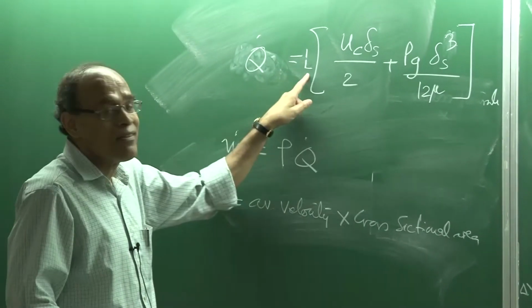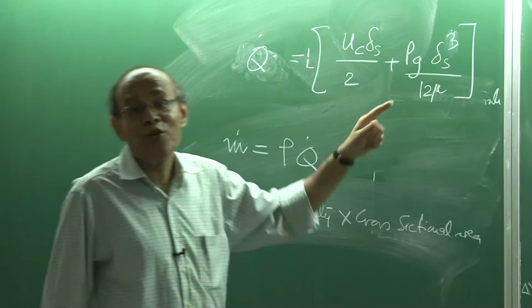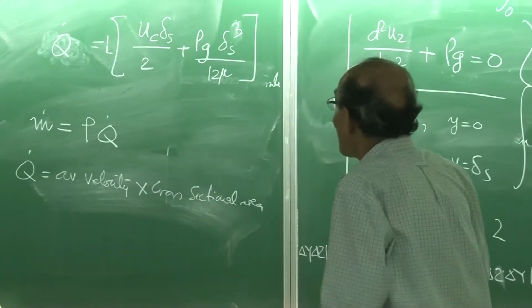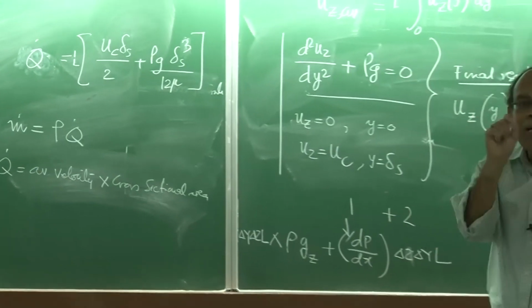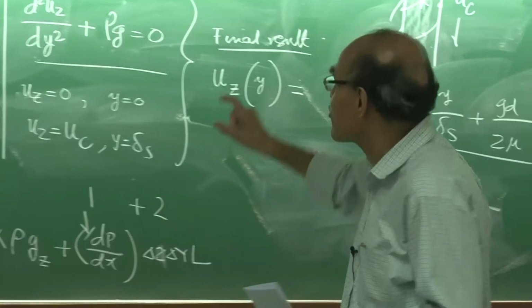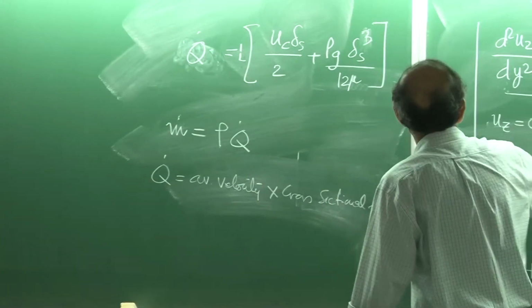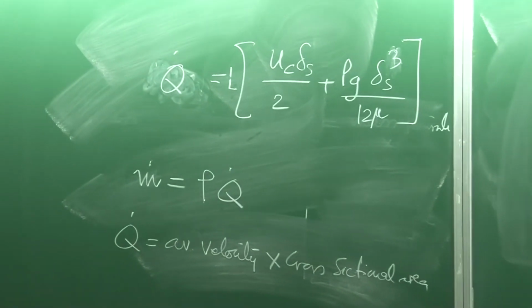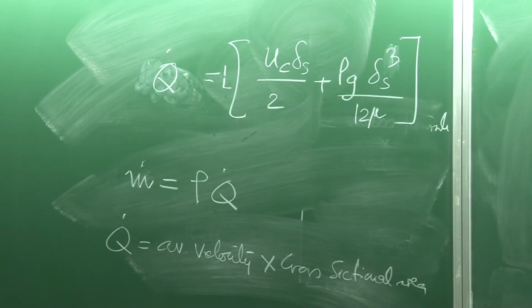If I do not write L, in that case I would say it is the volumetric flow rate per unit depth of the slab. That is the expression. Now, you can look at the beauty of this. I can do a simple exercise in the industry based on this formulation here. Casting speed values, for example, I know it is of the order of 1 meter per minute. You can check that this equation is consistent here.